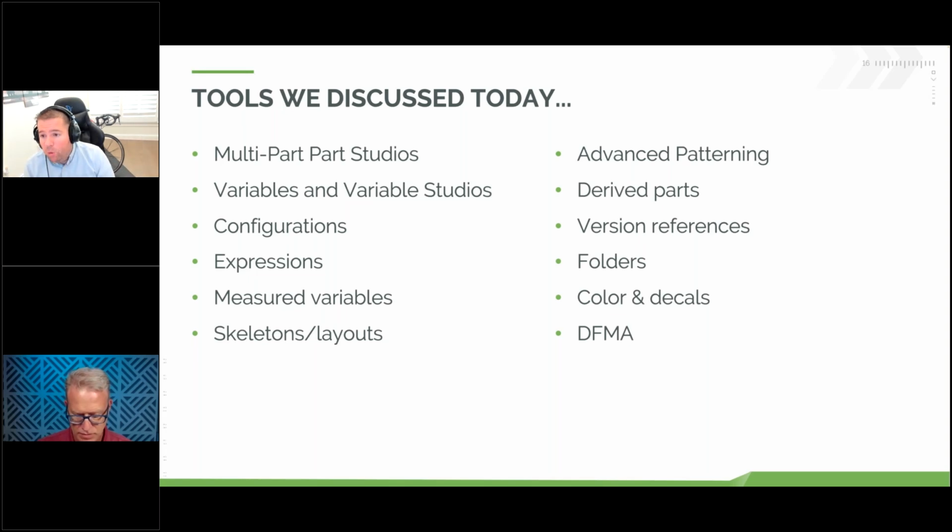So think for a moment, how's it going to be manufactured? Were the processes machined processes, cast processes, injection molded? And how does that define the type of features that I'm going to use and the way that I use them? Having those kinds of considerations before you begin designing can have a big impact on the choices that you make while designing. And I think that's the big takeaway.